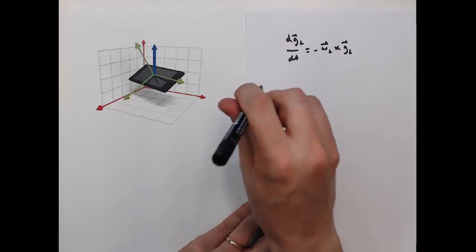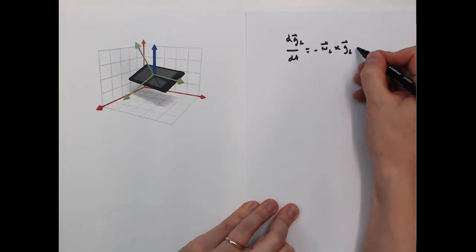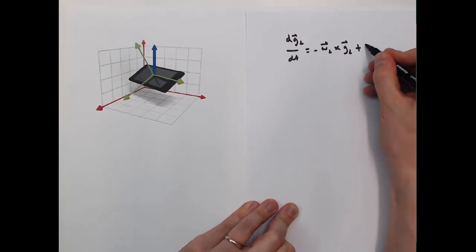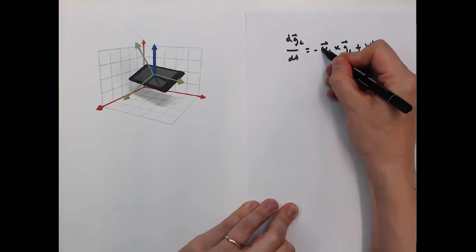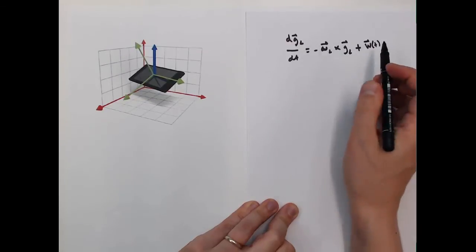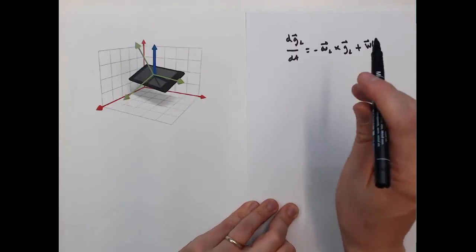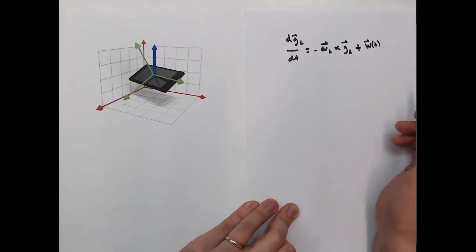But if you know the gyroscope measurement, you can basically calculate how it should move. But now the model is not perfect, so you typically want to add a white noise process here as well. So this is omega and this is W. Now this models the orientation changes and also the uncertainties in the mobile phone orientation.